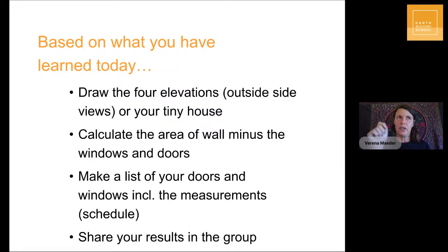So that you start going, how tall is the room? Where does the roof go? If I have a gable roof, how tall is that? What kind of timbers am I using? So that you really can check things like head clearances. It's a typical mistake that all of a sudden you go, oh, this window is too low or the door doesn't fit or something like that. So you need to really start putting the whole thing together in a three-dimensional fashion.